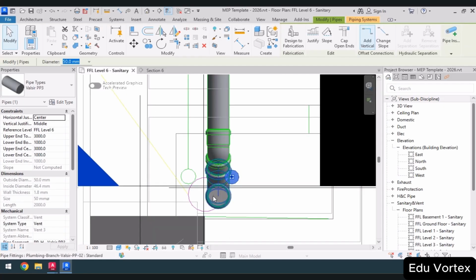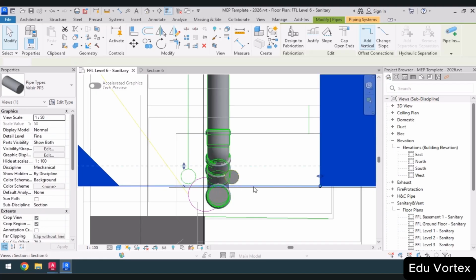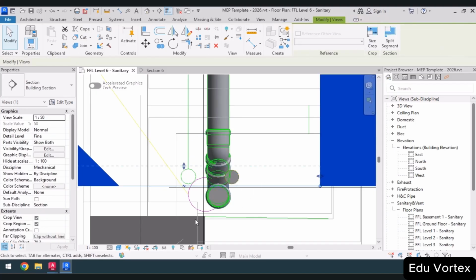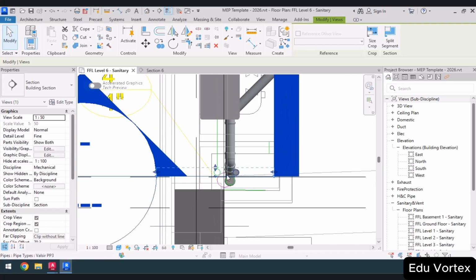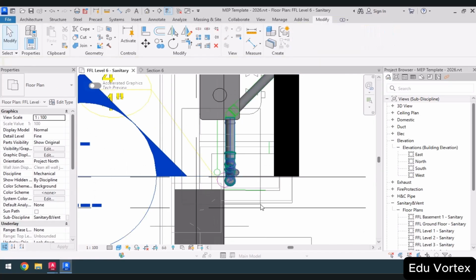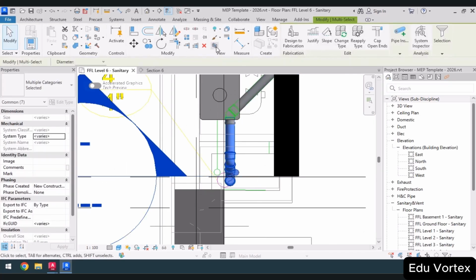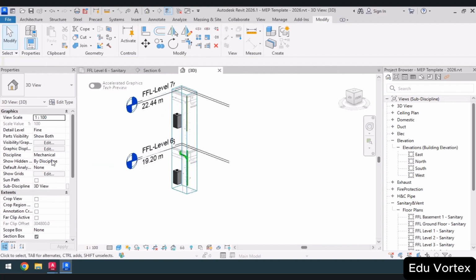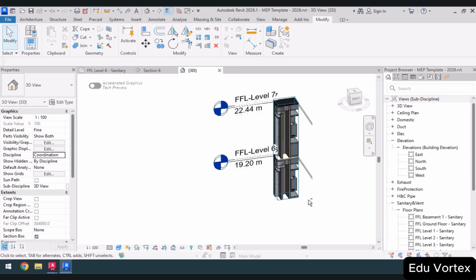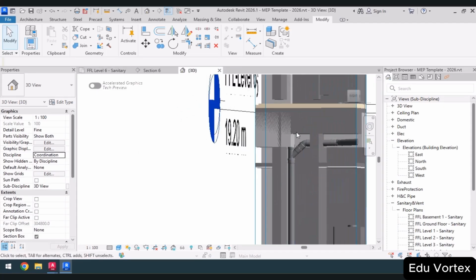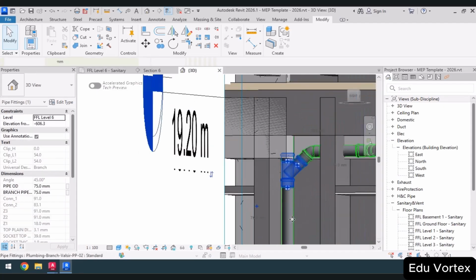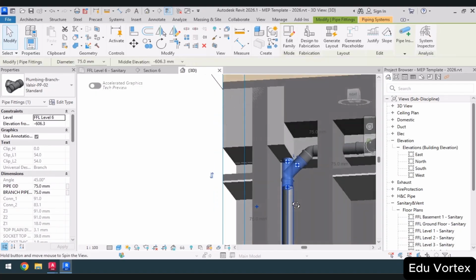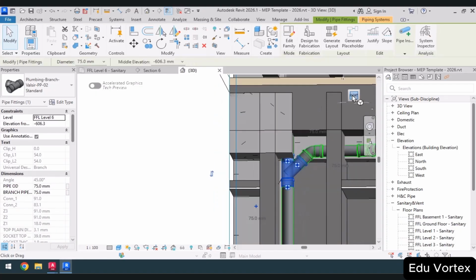Now this position is also interfering with the wastewater pipe, which is also obstructed by the beam in the current location. So let me select this section box and take a look at it in 3D. I will switch this 3D view to the perspective mode and rotate it a bit, coordination mode I mean. As you can see, it currently interferes with the beam.